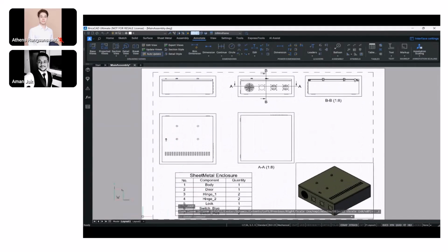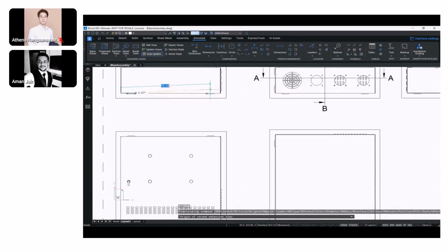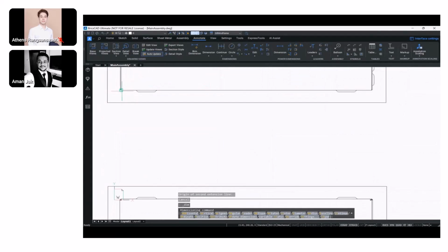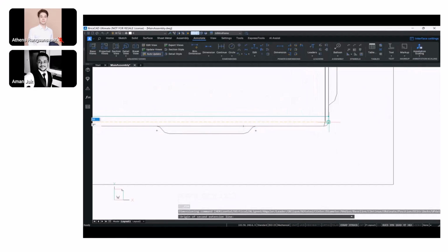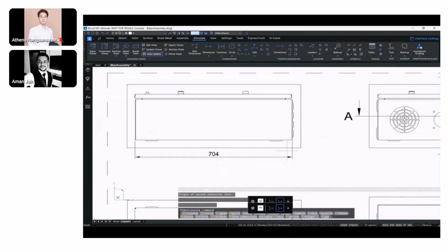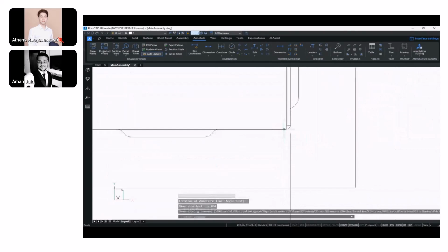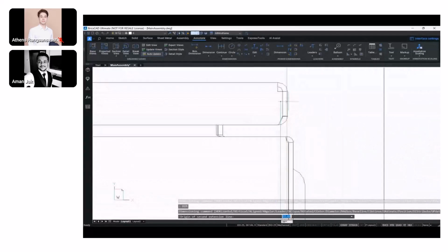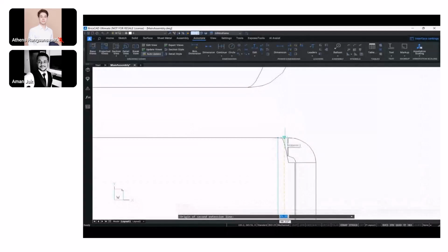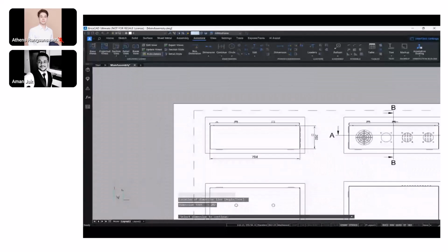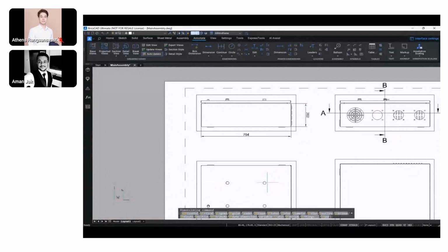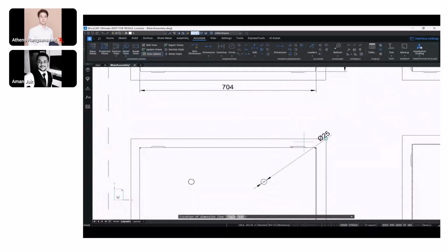Right. Last but not the least comes the dimensions. So let's say if we need to add dimensions, we can simply use the annotations in BricsCAD, a very accurate dimension representation. And the best part is, if we dimension this over here in layouts, and what I have personally seen happening is, we annotate the entire thing in a 3D MCAD tool, and when we bring it inside a CAD environment, let's say it could be something like AutoCAD or even BricsCAD for that matter, when it comes from a traditional 3D CAD environment, it kind of loses all its intelligence, right? The dimensions act like lines, arrows, and text. It all comes exploded. There is no intelligence whatsoever associated to the annotations that we place inside a 3D modeling environment when it comes to the 2D environment, right?